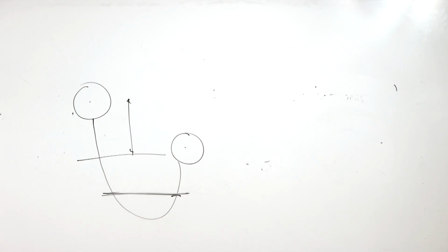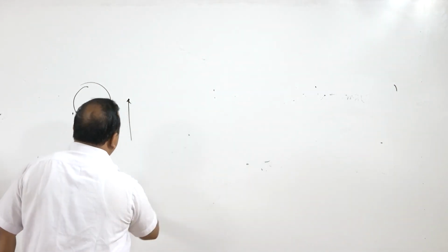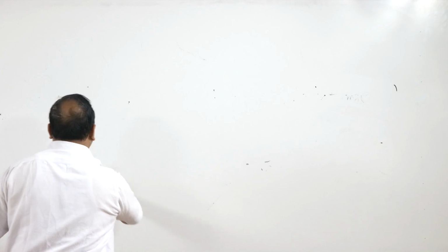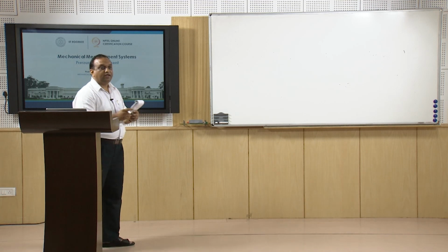Now, manometers are inexpensive and accuracy is also good, but they have poor response, or they are not used for the dynamic response of the system. They are very good for static measurement. They are suitable for low pressure. For high pressure, we cannot go.